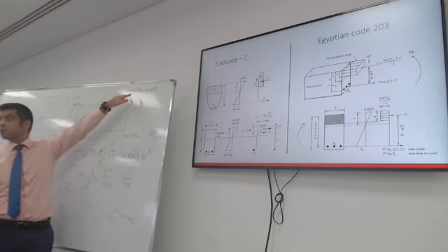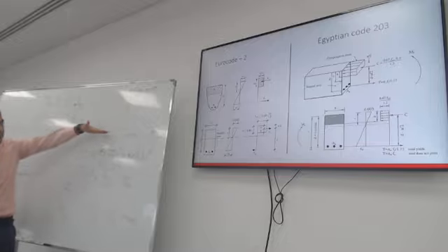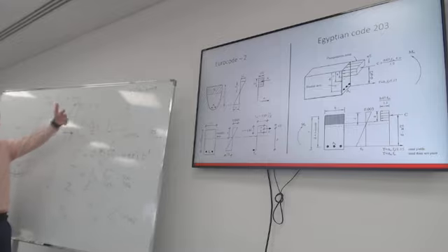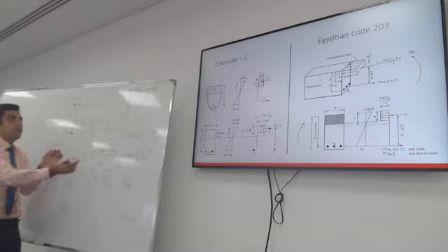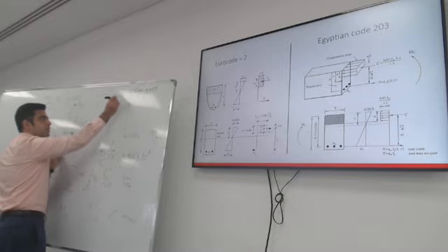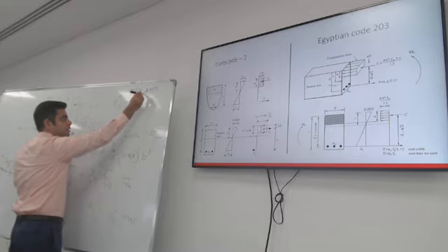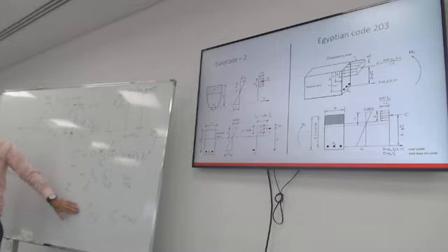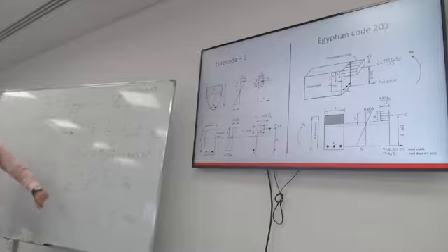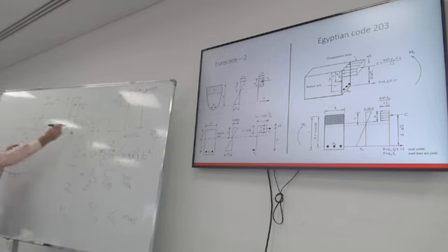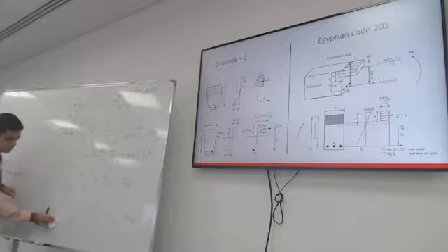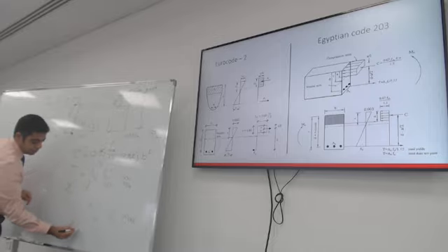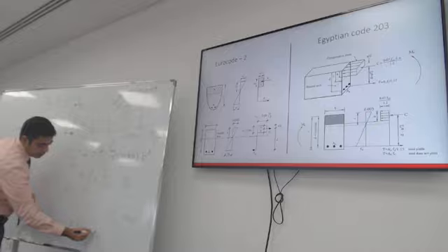I will limit the strain at the top, and allow the strain at the bottom to exceed yield strain, and therefore I should always limit the ratio X divided by D. In the example, you will find very quickly that we will use X to calculate this factor Z, and we will limit the ratio between Z and D to 0.95.